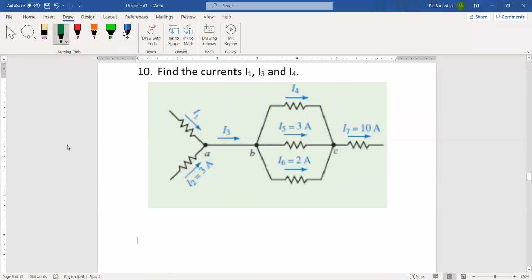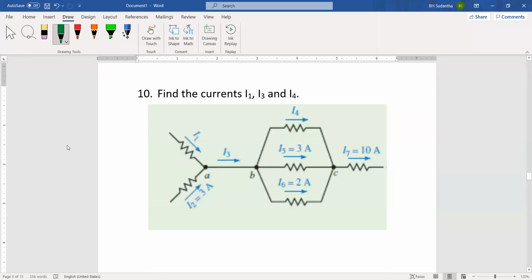Okay. Then if you're okay with that, this is another very simple question. And again, you have to use Kirchhoff's current law. You can see that outgoing current from this node is 10 ampere. Okay. Then one current is coming this way, it's 2 ampere. Then this is 3 ampere. Because of that, this 2 ampere plus 3 ampere is 5 amperes. And then this should be 5 ampere. That's why we can make 10 ampere. And 5 plus 3, 8 plus 2, 10. Then these currents are okay.